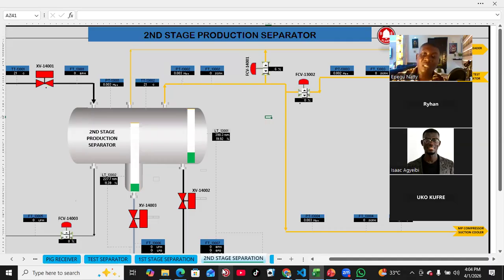What do you have? Do you have a PSV? Do you have, let's say, an overflow line, a line that when the level gets to that, it will open and then send it to another vessel? Do you have it? What are the modalities, right? Do you send your field operator to stand at the level gauge to be checking the level every minute, right? So these are things you ask yourself, these are things you discuss, you document, right, before you accept for a bypass of a transmitter, of an alarm to be carried out, okay?